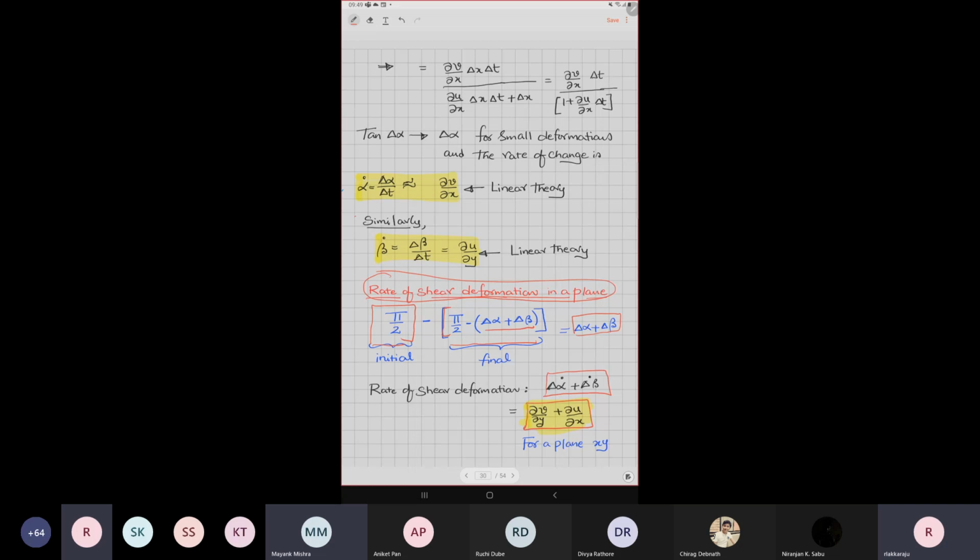So when you are taking an infinitesimal element, whether it is a ship crawling over the oceans, rocket exhaust, fan blades or gas turbine blades, you're trying to do some mechanical action. Because of that, liquid particles gain energy and momentum, and they are driven from one location to another, taking out your energy and deforming the material. They are going to do some work. Most of the energy you pump into the system goes into the liquid, to drive it, deform it, and do work on it. Because of that, heating happens. Whenever you rub things, naturally heat will be produced. In the same way, whenever fluid particles are deforming, some amount of energy comes out of the system, and that can be better quantified in terms of these deformation rates.